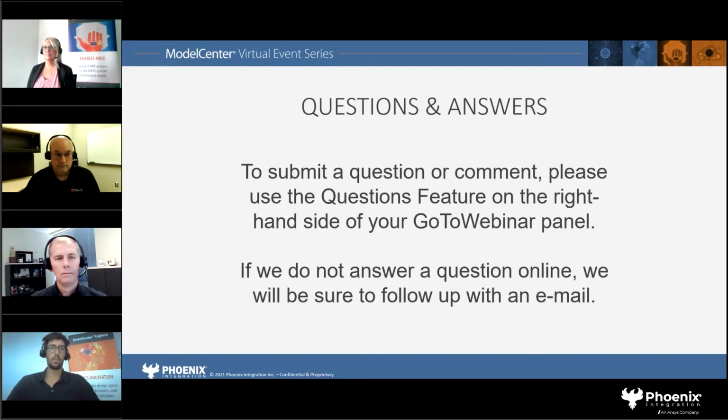And maybe David or Steve, you want to mention the small modification that came with GENESYS 2021. I think you have another interface now for the parameter definition in which you can be more precise. You can define not just an objective and a threshold, but a minimal and a maximal value. So bounds, an interval for each parameter.